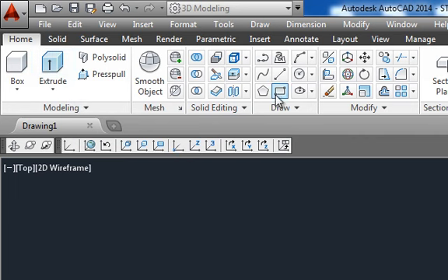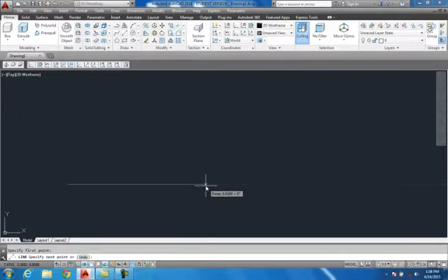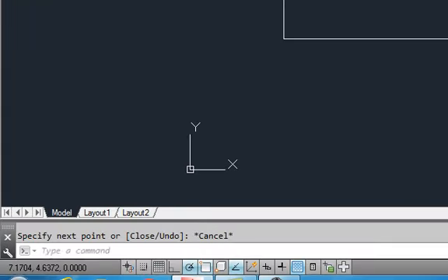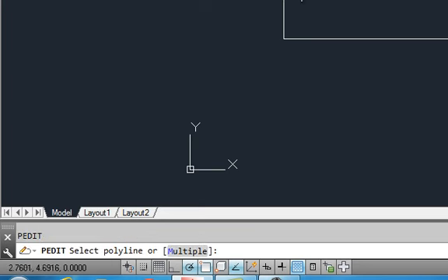First thing you got to do, if you want to draw a region, is you can actually go in here and draw something up from a side view, a profile shot of it. And after you get that profile, you have to put it into a polyline. Now, to put it into a polyline, you type in PE, enter, and just select. Polyline edit, you can do different things with it, and it's asking you what line do you want to work with.